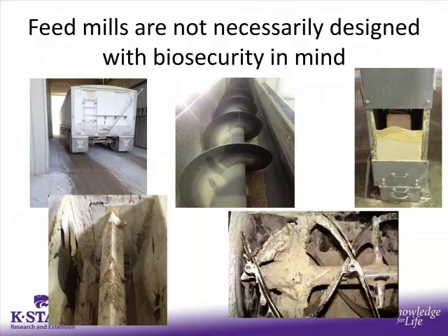And so what you have right here, similar to slides that Laura's also going to show, the receiving pits are a major concern when people are driving across the pit with a dirty truck. But also what you see right here, these would be considered a clean screw conveyor within a feed mill. Normally in a feed mill, we define clean as that point at which no more feed is exiting the system. And so you can still see there's going to be a certain amount of feed at the bottom of this. Here's the bottom of a bucket elevator, really high risk area right here.